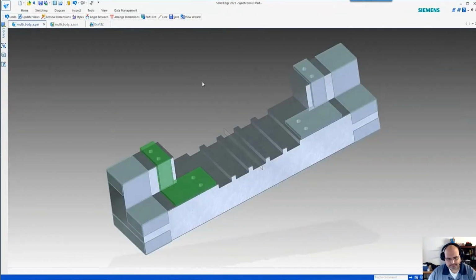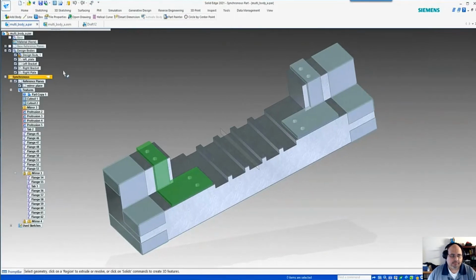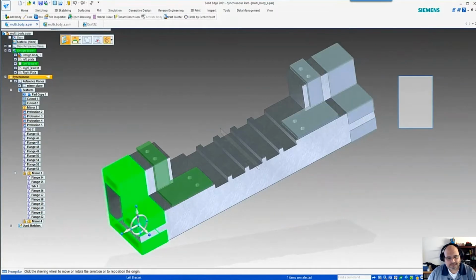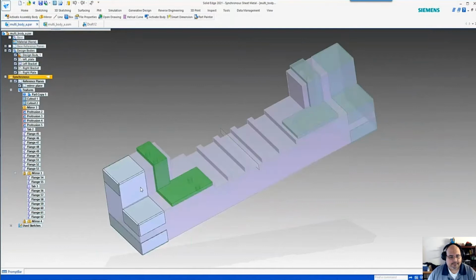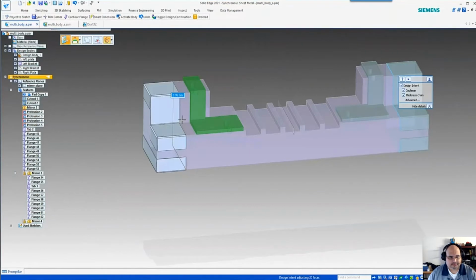And there you can see now I have balloons and callouts for each individual component piece. So if I go back over to my original part, remember this is the one driving the rest of the model. So if I go in and activate, say, this left body piece, I can activate it. You'll notice the color shift. Now I'm in a sheet metal environment because I'm kind of in place activated. And say I want to go ahead and drag this face out, make a change.